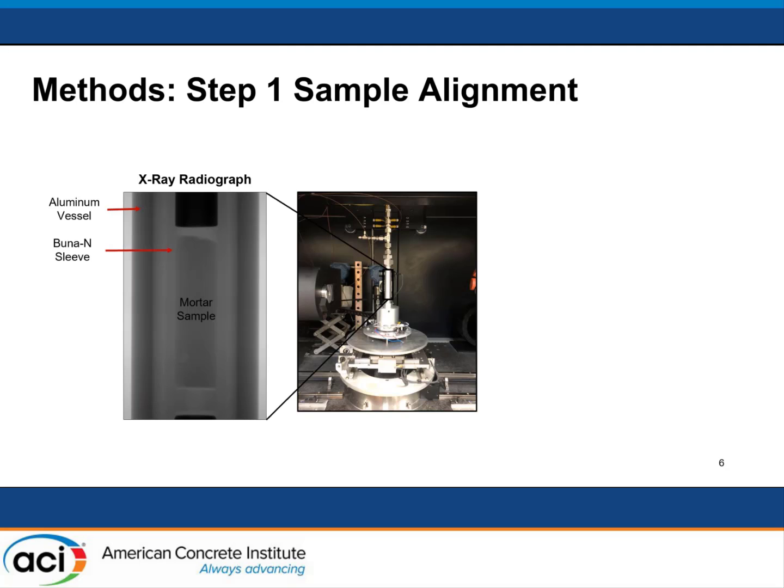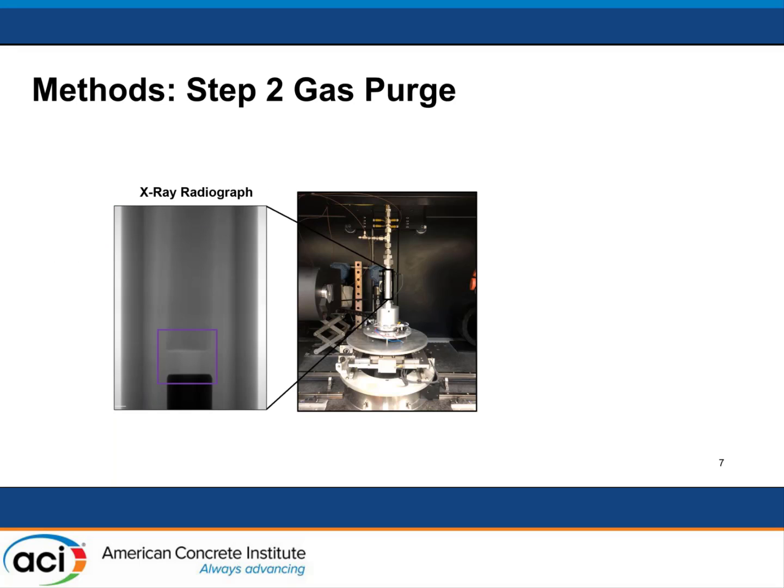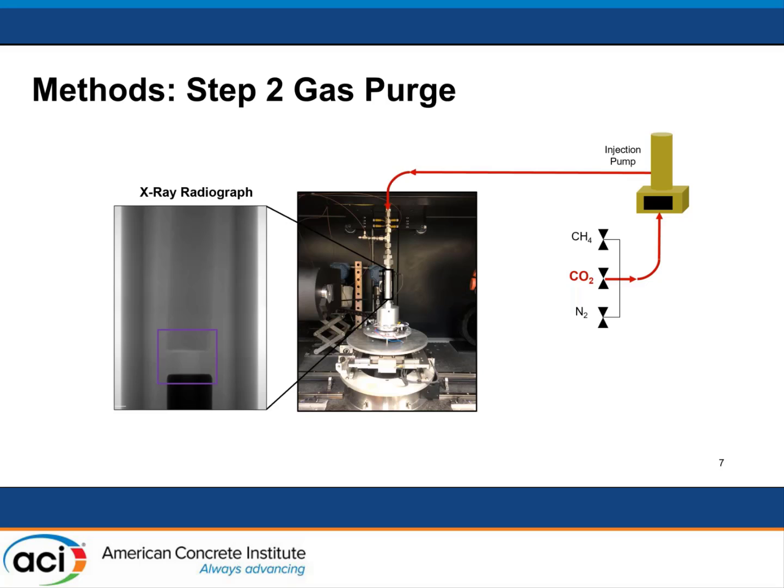We have a sleeve that connects the inlet and outlet injection ports that are above and below the mortar sample. And then we have a Teflon spacer, which I will talk about more. It's really only important when we discuss the water injection. And then, yes, the injection port for the gas. So we then come in and we inject a gas phase. So we want to remove all the air from the system. So we injected CO2 into the system overnight. So we basically just did a pressure gradient across the injection pump to the receiving pump.